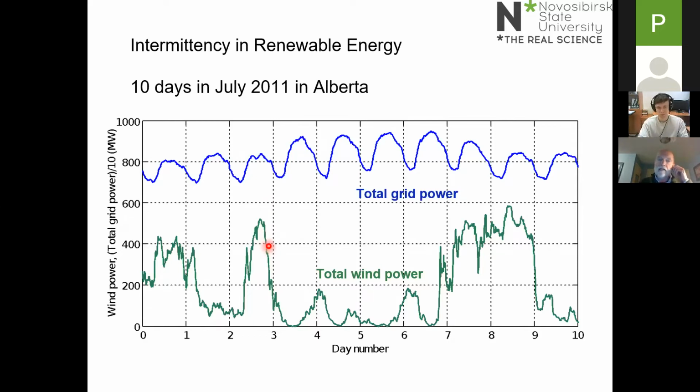And the current technologies of generators that fall into that category are gas turbines, and we saw a little bit about gas turbine installation in the US yesterday, and hydropower, believe it or not. Some types of hydropower are also relatively easy to ramp up and ramp down.